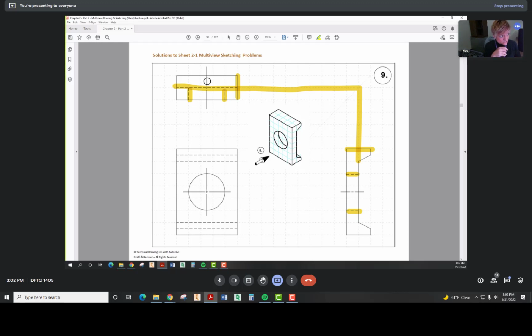Now this axial center line, I would only go beyond that circular object with a dash, and then out here beyond that circular object. In other words, this is too long. I wouldn't make that long beyond the square object. But don't let it connect to that horizontal edge. Just for clarity's sake. Any questions on that?